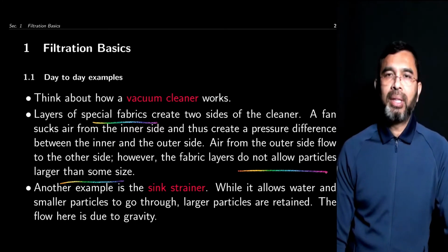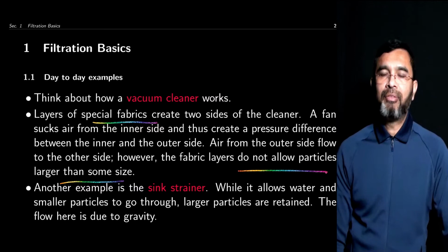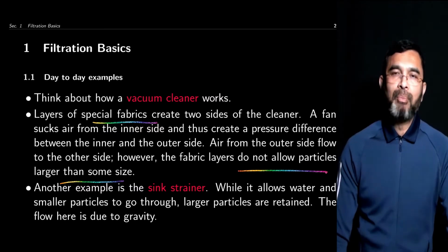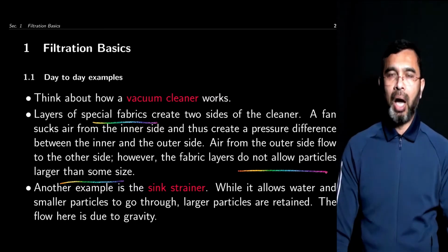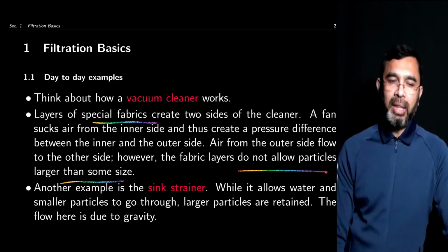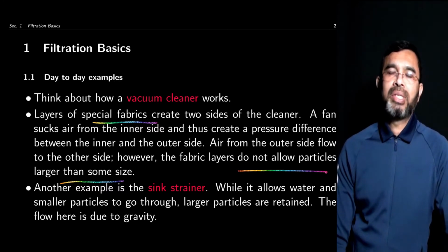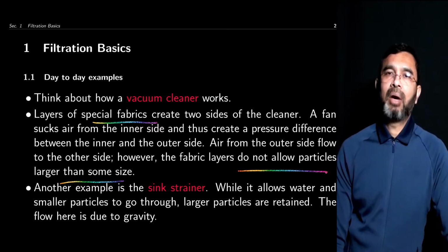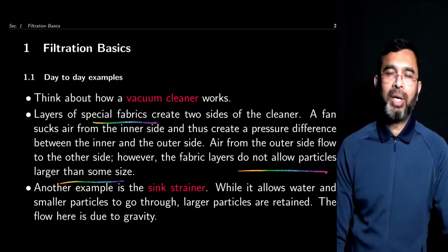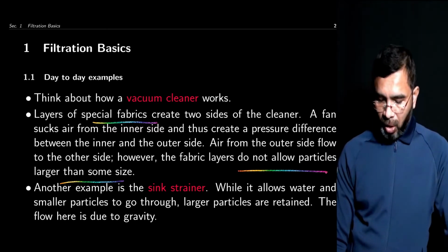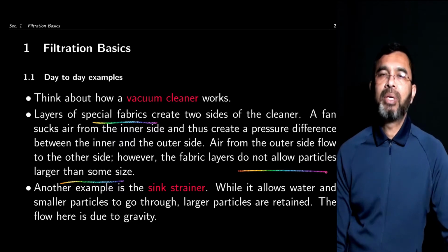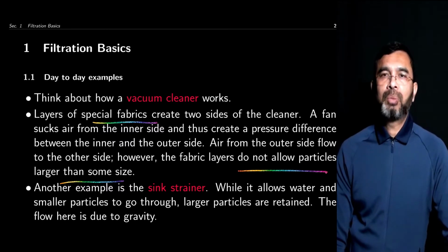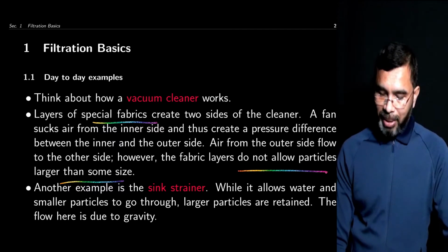So what happens when there is this pressure difference between these two sides? Air moves through the filter medium. However, the solid particles in the air are trapped on one side of the filter medium. That's how separation takes place between air and those particulate solids. So that's the basic operating principle of most filtration processes. However, the driving force for this movement of the fluid may be different.